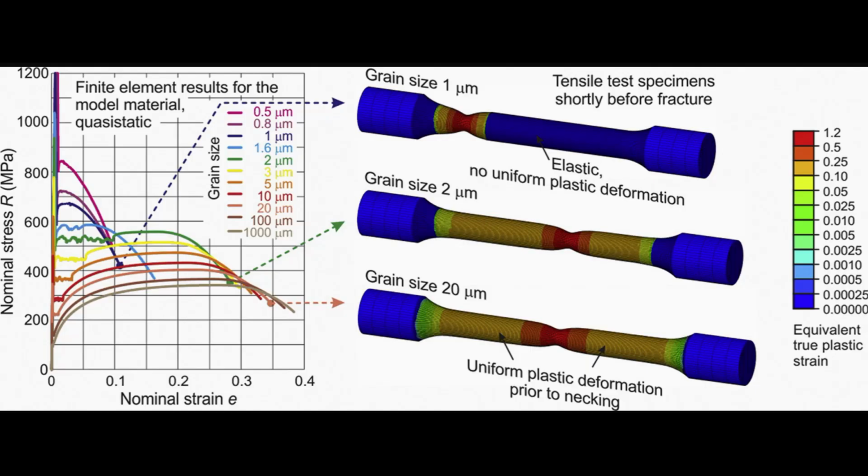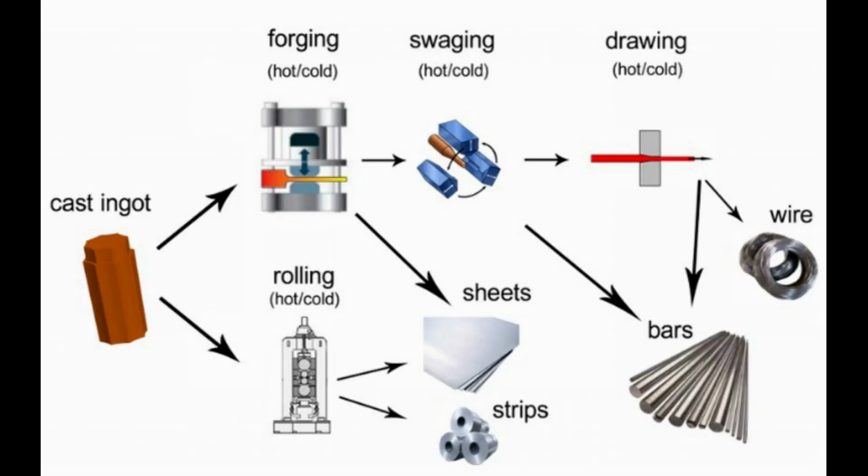ultimate failure. Thinning. Thinning is a failure mode that is often associated with materials or structures undergoing plastic deformation. It specifically refers to a reduction in thickness or cross-sectional dimensions of a material or structure as a result of plastic deformation or other deformation mechanisms. Thinning can occur in metal structures subjected to plastic deformation processes, such as forming or stamping. In such cases, the material experiences localized plastic flow, resulting in a reduction in thickness in certain regions.